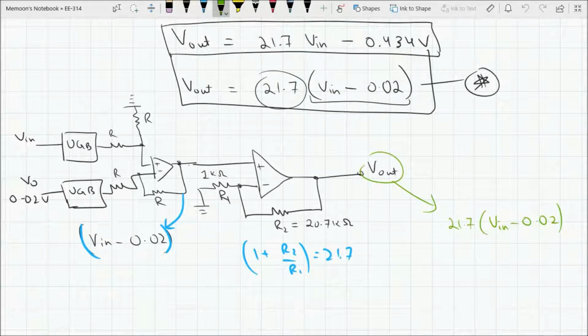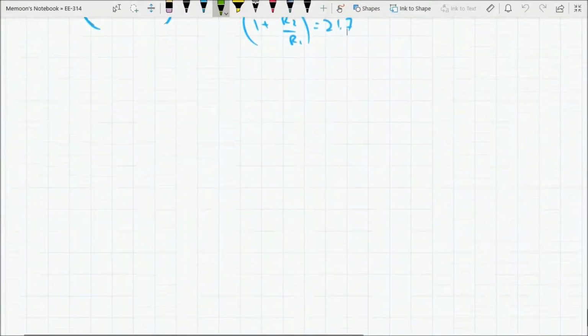So I hope now you know which steps we have to follow to convert a simple voltage range from one set of values to another set of values. We develop equations, we solve the equations, we find the unknown parameters, and then we develop a final relationship between the V out and V in, and we will probably have some offsets and some gains that we can easily manage by using different configurations of the operational amplifiers.